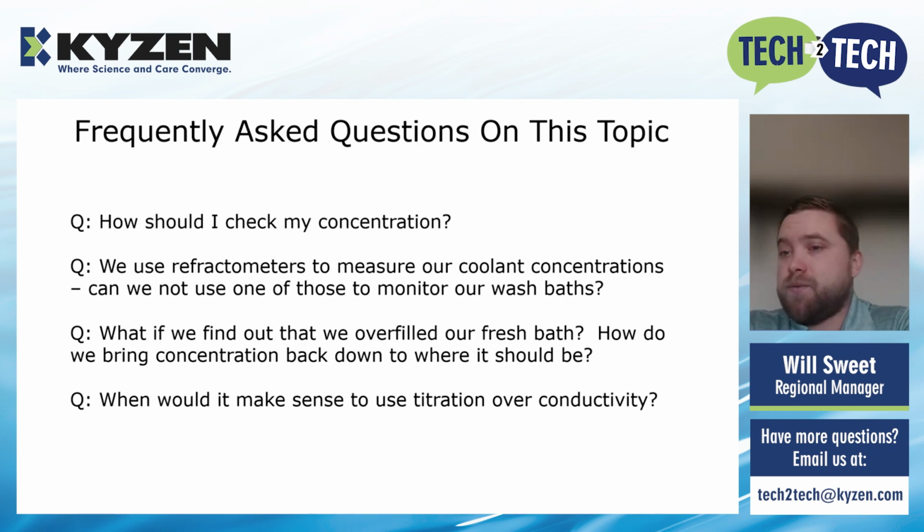You cannot use a refractometer, at least with any of our products or really any other product that I've run into. And that is because refractometers are not able to tell the difference between oil and chemistry. It sees it as the same. So if you have a very dirty bath or just a regularly dirty bath, it's going to mistakenly read whatever oil is in that bath as chemistry and give you an artificially high reading. So in that sense, it is just going to be incorrect unless it is a very clean bath, very fresh bath probably.